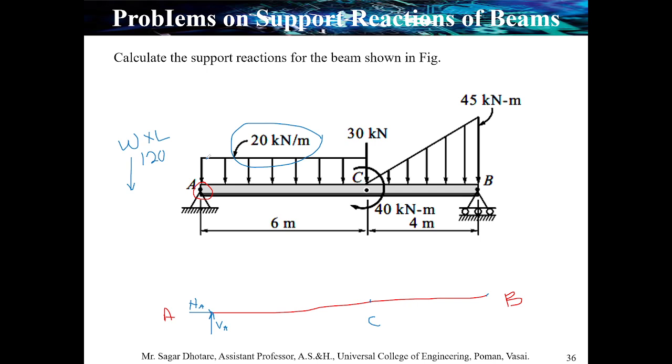Okay. Now we need to place this single point force in the span of 6 meter only, because it has a span of 6 meter. To calculate the distance from A or C, we have an equation. Let us say the total length is L; after the conversion to a single point force, we can place it at L by 2. So the remaining span is also L by 2.